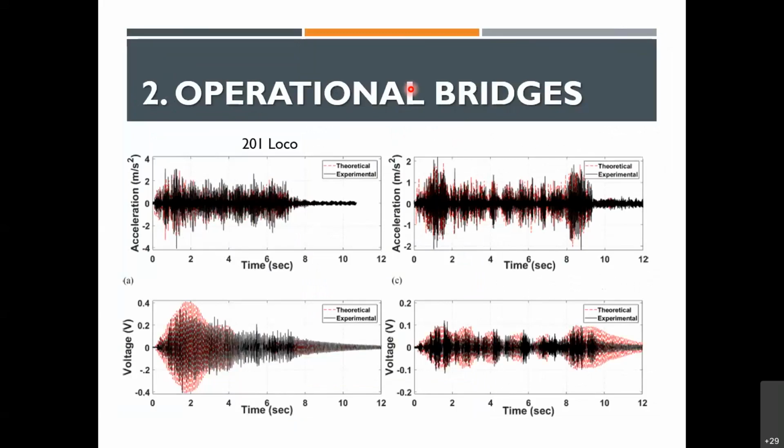And as you know, for most infrastructure, it's very hard to get permission to go in there. But what's interesting is that in most bridges, the accelerations that you see tend to be definitely less than half a G in most cases. And also the amplitude of displacement tends to be only a few millimeters.